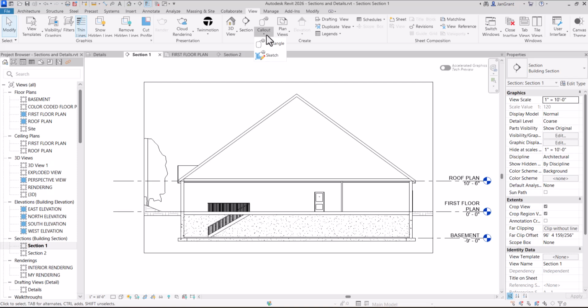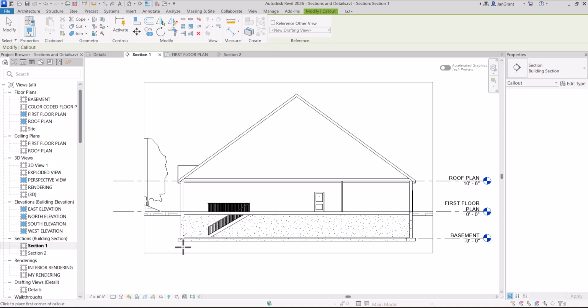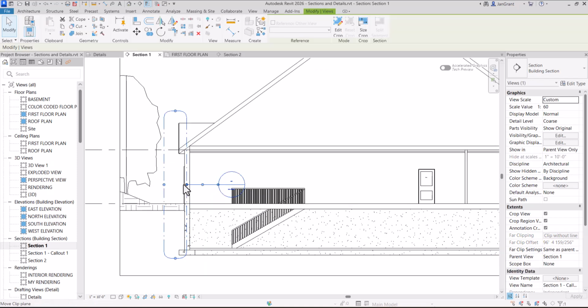So if I, for instance, create a rectangular callout up here on my section, I can click a point, pull my mouse across here, kind of like decide on where I want that whole wall section to go. You can even pull this label over here. So now you've got a callout, you've got a section, and see how it's called a callout there? So there's a connection to what's going on in the drawing, and not just a wall section, right? So if something changes in either one of them, it will update.